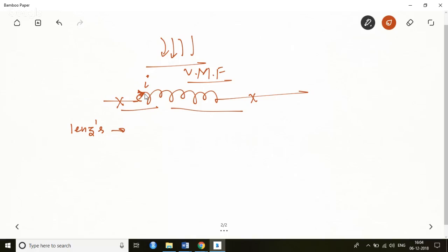It means that whichever magnetic field is producing this particular current inside this conductor, the current would be in such a direction that it opposes this magnetic field. Or let me directly go to how to find the direction of current. The direction of the current by Lenz's law can be found by Fleming's right hand rule.